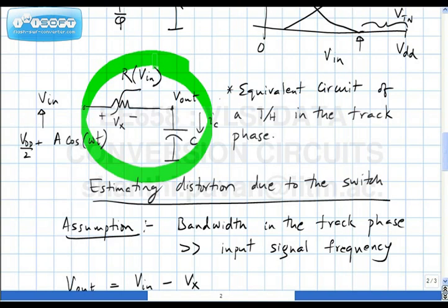All right. Now, when you have a nonlinear switch, the continuous time voltage waveform across the capacitor has got not only the input frequency but its harmonics. So when you open the switch, the charge trapped on this capacitor forms a sequence, for the first clock cycle, second clock cycle, and so on. When you look at this discrete time sequence in the frequency domain, what frequency components do you expect? You will expect to see frequency components not only of the fundamental frequency but all its harmonics.